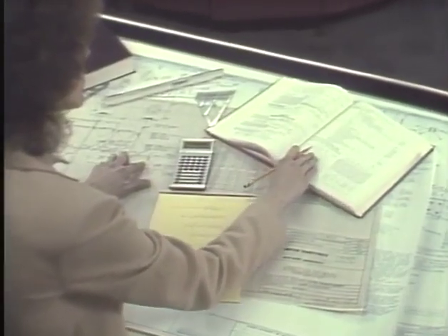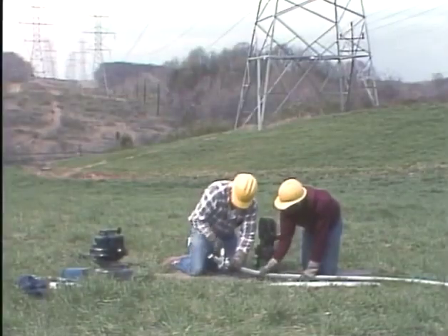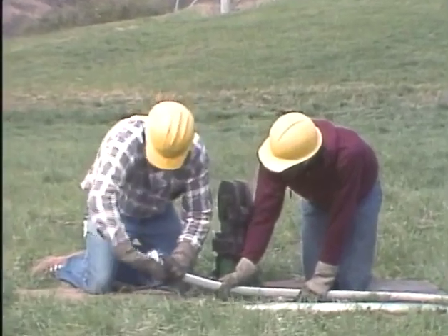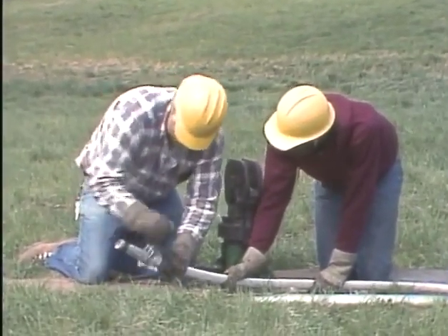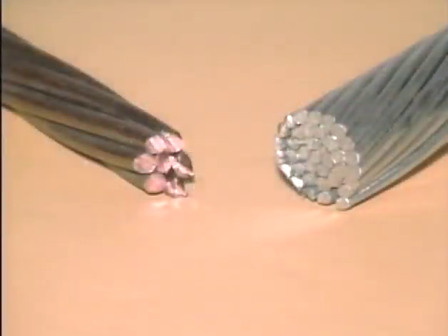You must ensure that these systems are installed and maintained according to design specifications so that all the preventive measures established on the drawing board are effectively put into action on the line. This includes things like making proper installations according to design drawings and making good conductor connections to maintain reduced resistance and power loss. You should follow your company's procedures for crimping and cleaning conductor connections and splices. And you should always be sure to handle conductors with care. Avoid nicking, bending, and dragging conductors to help reduce corona effects.